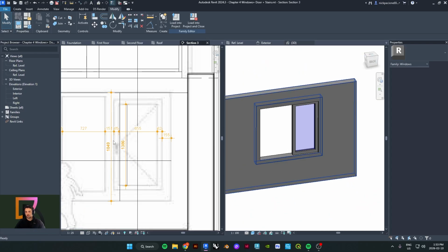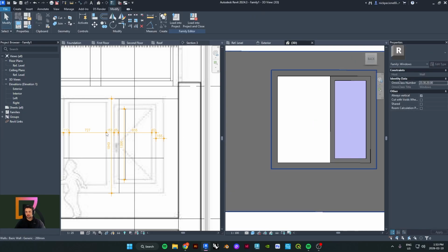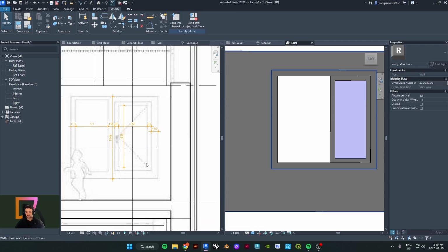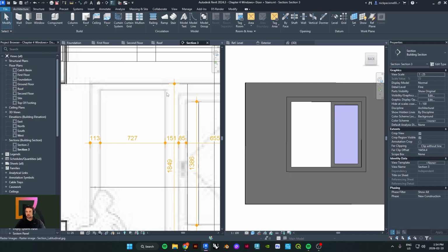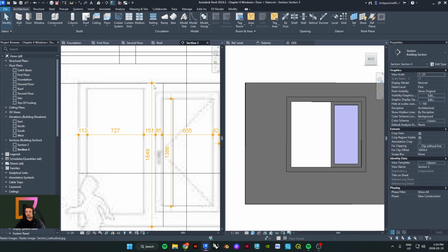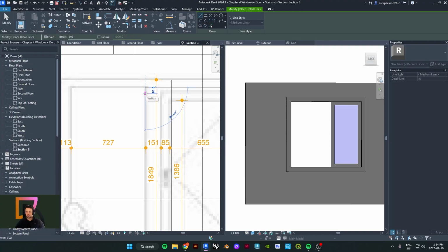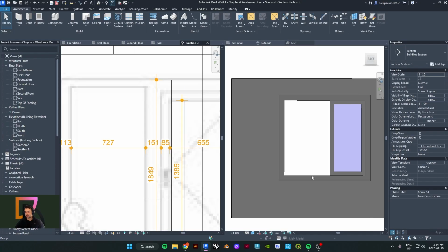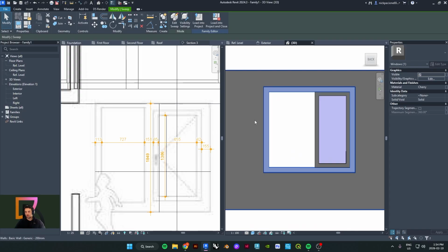And now we need this kind of larger pane, which will simply just be an extrusion. So I'm going to do that. I want to have this kind of offset here. If I find out what this offset is, which is about 60 millimeters, I can go into the sweep that we made, this first sweep, and I can actually